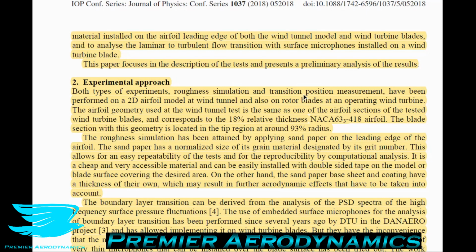This is very important to note because wind turbine blades do not have a constant profile along the entire span. It does change. This is for a couple of reasons. One, as you go along the span, you get a greater rotational velocity, so a greater translational velocity, because the rotational velocity is the same, but you're further away from the point it rotates about, so you get a greater translational motion.